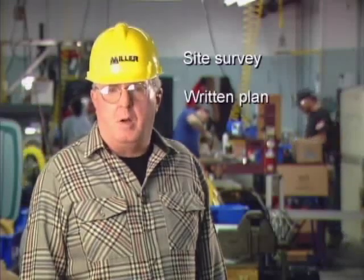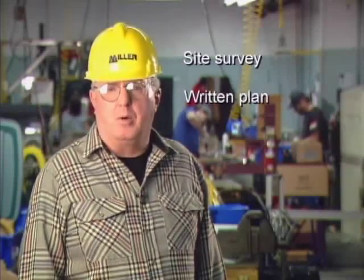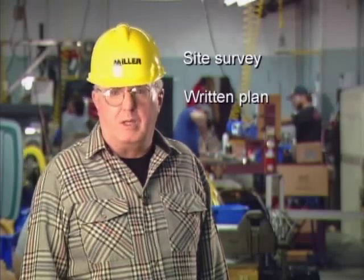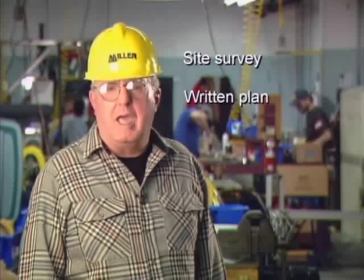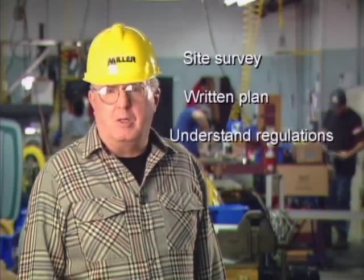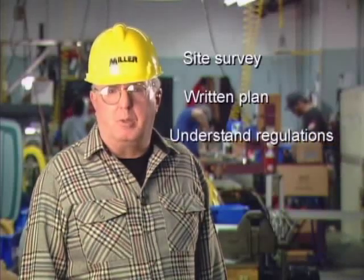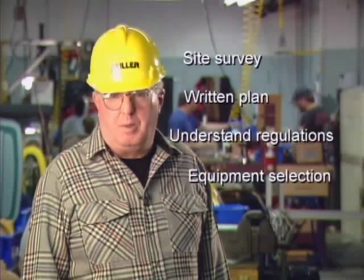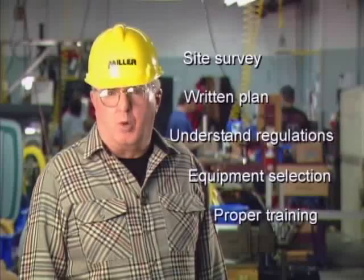Identification of all predictable fall hazards through a site survey conducted by a qualified person. A written fall protection plan that details the fall prevention and protection methods to be used for each hazard. The proper fall prevention and protection equipment for each hazard, and rescue plans. A thorough understanding by all workers of applicable standards and regulations. Proper selection of fall protection equipment, and a comprehensive training program for all workers. In order to be effective, all parts of the program must be in place and working together.